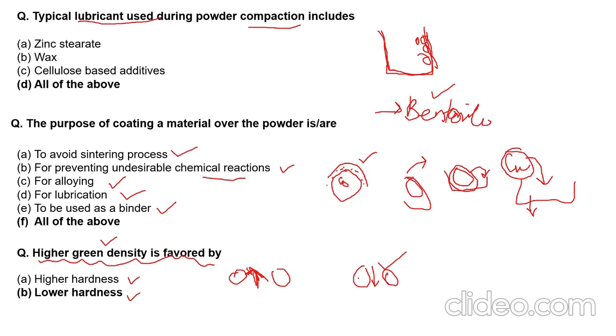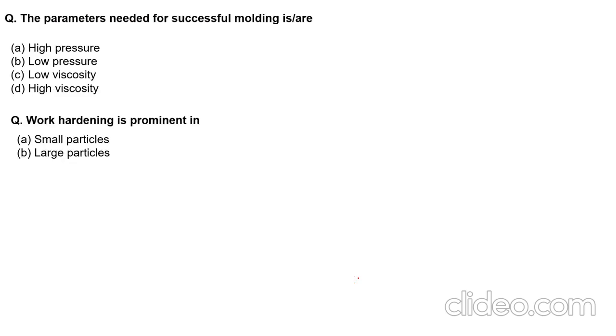Based on your particle characteristics, we have to understand the particle shape, particle morphology, or particle size. We also have to identify the particle characteristics in terms of hardness, roughness, or smooth surfaces, and how the surfaces behave. All of this will influence your compactability and flowability in a compaction process, and their density subsequently.